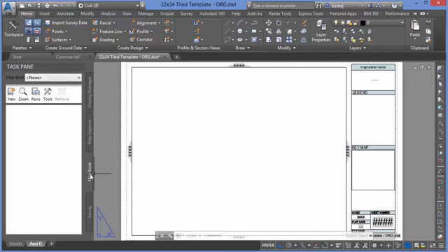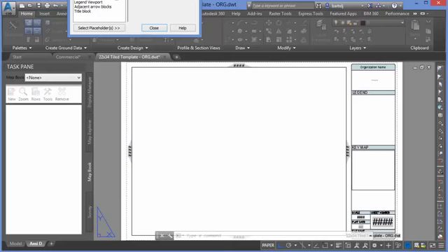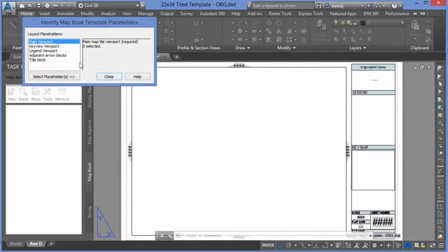There is a tab here that's called MapBooks, and the first thing that we're going to do is define how these viewports should be utilized in the process of breaking out these sheets. So I'm going to go to Tools, and I'm going to identify template placeholders. When we do that, it brings up a utility for us on the screen, and then we can walk down and identify those different components that make up our sheet.